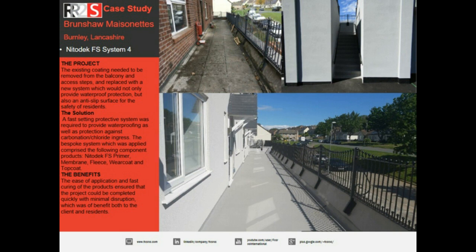So we made sure that we worked in conjunction with an applicator that we had a lot of respect for, and that we'd done a bit of training with on the product as well. A company called RAM Services did the work on this project. First thing they did was stabilise the slabs and make sure they had a nice clean surface, and any surface deviations, the pointing lines and things like that, were filled in to make it as good, flat and stable as possible.